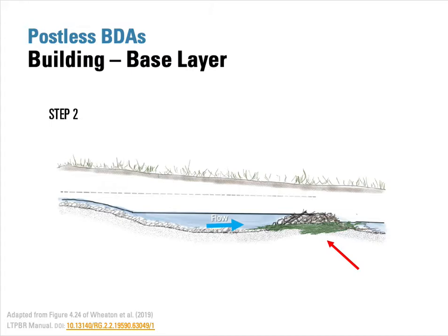So once you've got your spot, you can lay some branches parallel and then start to pack down fill material of cobble and dirt and sod. And you want to build these in small layers of 1/2 foot to 1 foot, trying to seal them up and keep your crest elevation uniform.